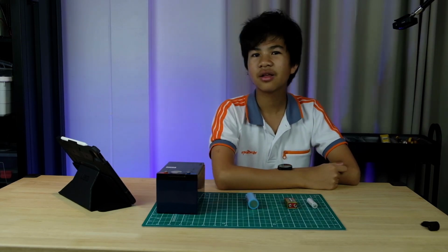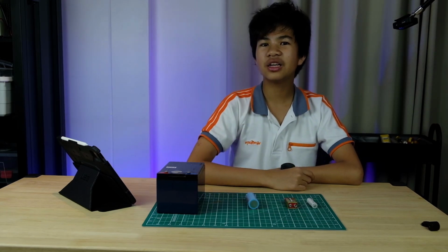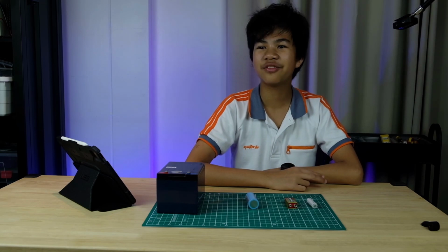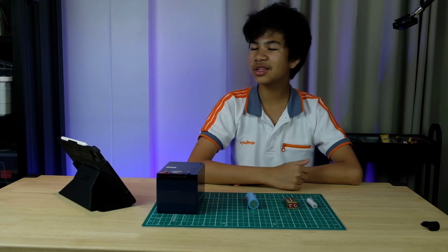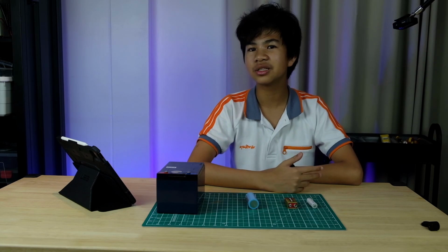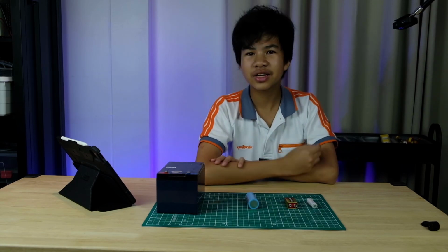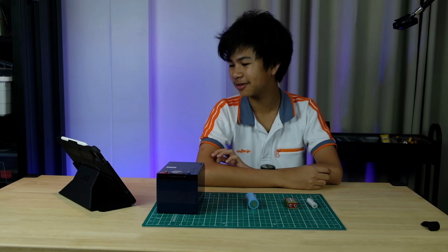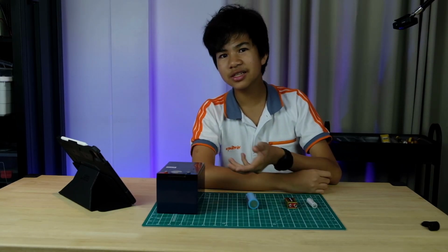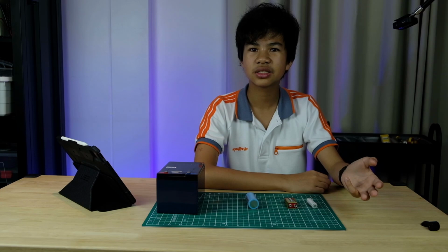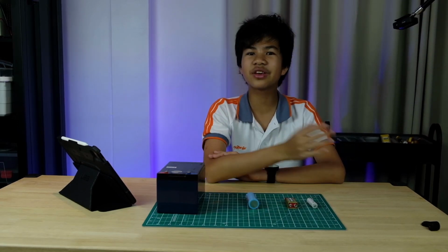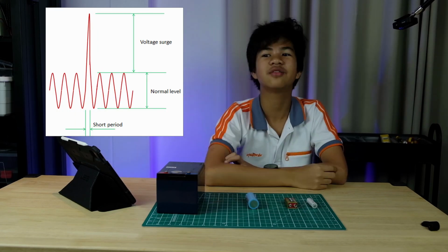Oh, and also, flooded batteries should not be operated upside down because that will affect the battery quality and their output. But sealed batteries are fine. You can do whatever you want. Pretty sure it's not gonna explode. So that means sealed batteries have less maintenance, but usually they come in smaller sizes. Like if you look in your car, it's like 200 amps or something crazy like that, and they can tolerate a peak amperage for starting your car.